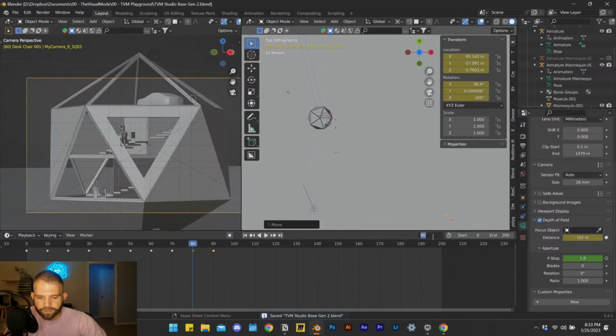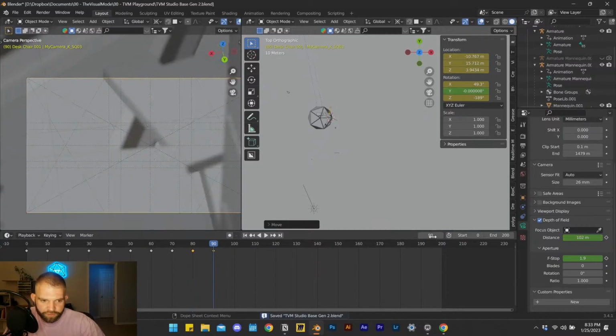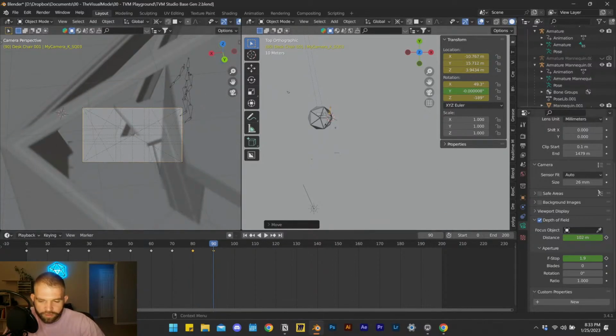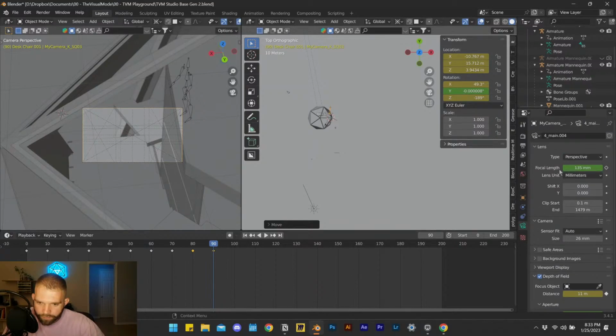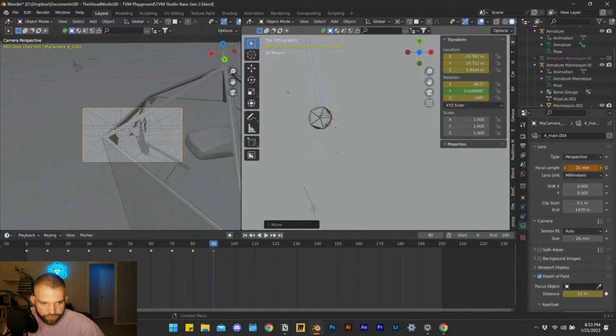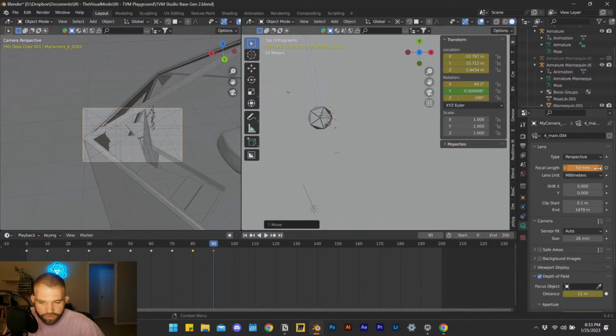I'm going to go back to 90. Make sure that I still have that shot looking down on the stairs. Yes, but not only do I have to re-keyframe my focal distance. There we go. So my steps are in focus. But the focal length as well. I'm still way too punched in for this one. So 50 right here is going to do for that one. And keyframe that. So 80 and 90 are set, save for the character. So I'm just going to keep going with the camera and then come back and do all the positions for the character.